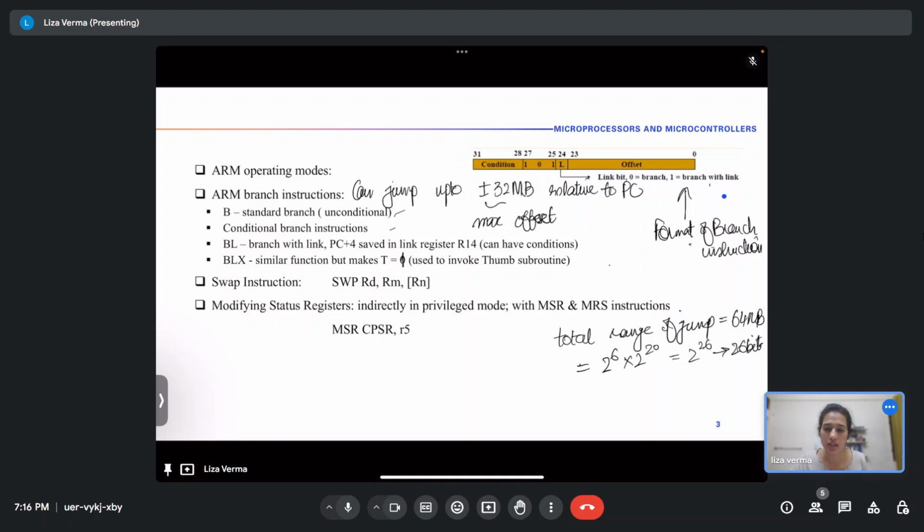But because we have the memory stored as these four parts, all the instructions, all the memory spaces are aligned in these four parts, four columns, or whatever you like to call it. So for every instruction, or for every starting of that memory location you want to locate, the first two bits, like D0 and D1, are always going to be 0, because the address is always going to be a multiple of 4.